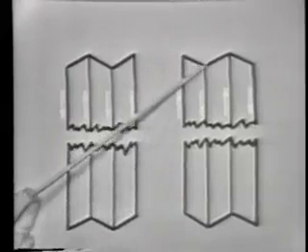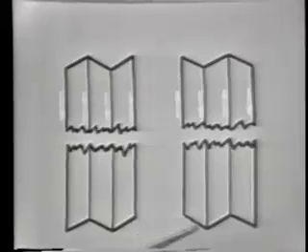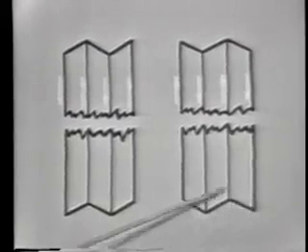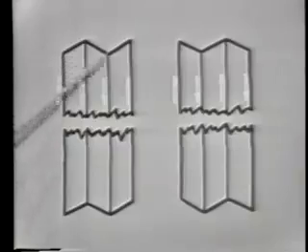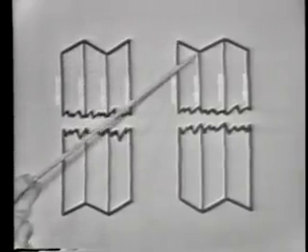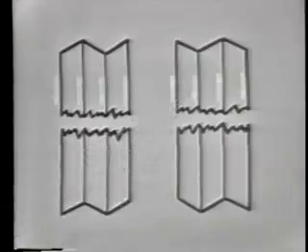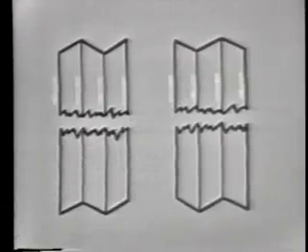Here, the deformed layers for the other alternation. And let's notice that the deformities are opposite for each alternation. Now, if the crystal is made to operate on the 5th overtone, it breaks down into 5 layers. If it's made to operate in the 7th, it breaks down into 7 layers and so on.